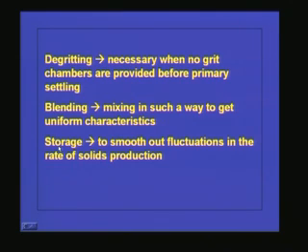Now coming to storage: its purpose is to smooth out fluctuations in the rate of solids production. The solids coming from the different treatment units are not continuous in nature. For the screens, whenever the screen gets clogged and the pressure drop is more than the permissible limit, only then do we go for cleaning of the screen. Once the screen is cleaned, we get the solids from the screen. So definitely it is not a continuous one.